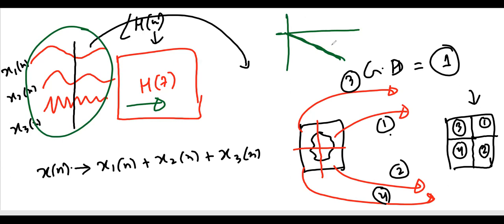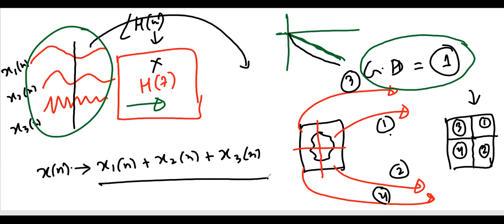You can apply the same delay to each and every signal, and you can get back your original signal by knowing this group delay number. But if you have a nonlinear phase response, it is very difficult to understand when and which signal actually penetrated through this filter, when you are recreating your original signal by combining all the signals together.